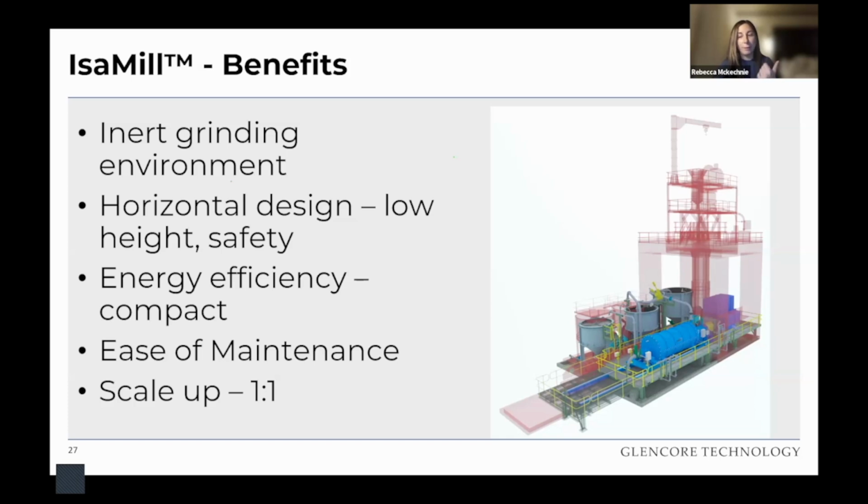For maintenance on vertical mills, obviously a crane is required, and space needs to be available to allow site to lay the shaft down when they've removed it. So the result is that the footprint requirement when moving to a vertical mill isn't as different to a horizontal mill as people might think.